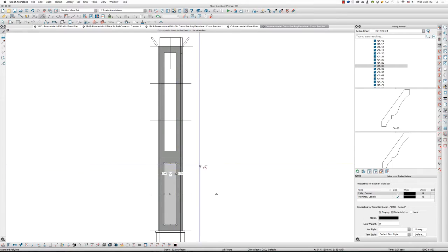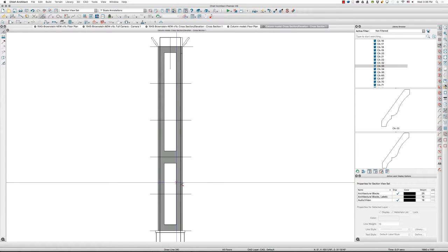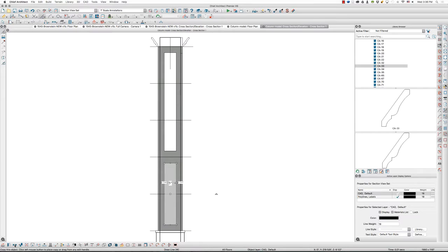Now I'm going to hit the W key on my keyboard, goes to our line tool, because I want to select that polyline and I want to copy this up here. So I'm going to try point to point. X, point here, point there. Let's get back into default mode and drag this up like so.